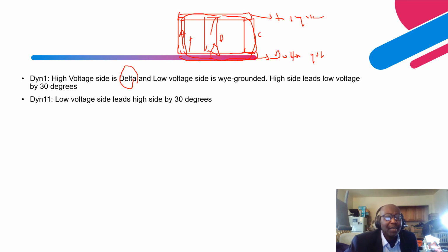On the surface of the core, right? Remember the core is a ground plane, right? So to protect the low voltage winding, you have an insulation layer that is put on the surface of the core, right? An insulation layer made of paper, and basically that is wrapped around the core. Then they put the low voltage winding, basically they slide it on top of it, right?